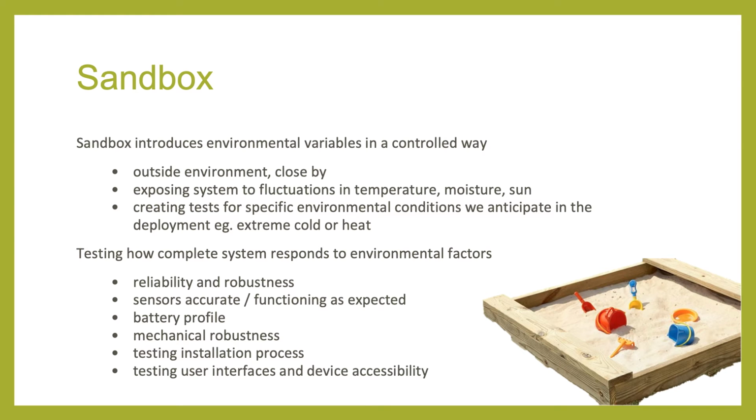This exposes some uglier issues since humidity and temperature will change the shape of the circuit board and can cause intermittent failures due to bad solder joints. So basically, we're testing for reliability, sensor accuracy, and building a more realistic battery profile. Importantly, we're also testing how robust our enclosures are. We're checking if water gets inside the enclosure, condensation builds up, the system gets too hot, etc.